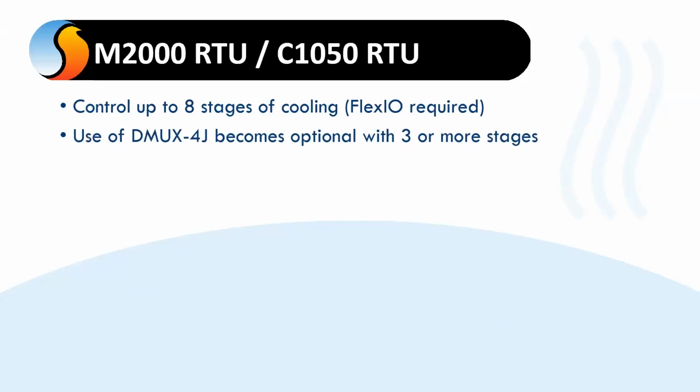The Demux now becomes optional, and we actually have the ability to recover DO2 and DO3 as digital outputs, and we can use those for your Y1 and Y2 calls for first and second stage cooling. And rather than have it sitting there blinking away, being a waste, and not being able to make use of those outputs that you paid for.